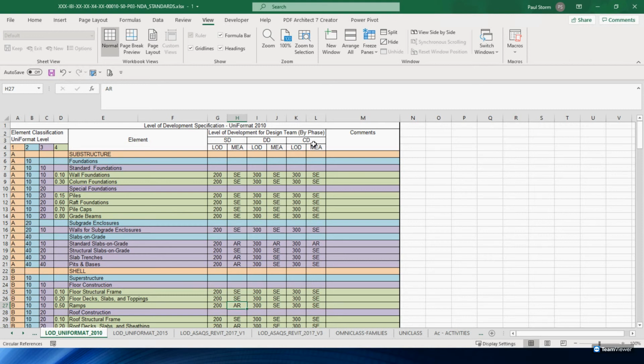Where it becomes critical is with the MEP services, because when you switch out a family, the families disconnect from their systems. So we usually ask the BIM managers to accept a final grade for MEP families because we don't want them to disconnect from their systems. That is down to management. But why would you want something like that?